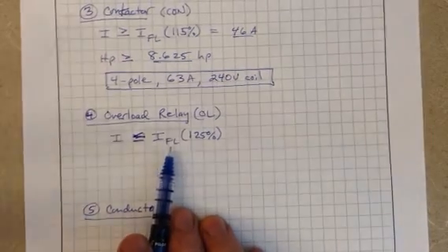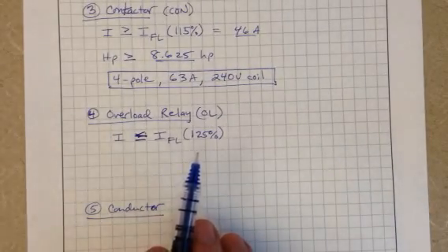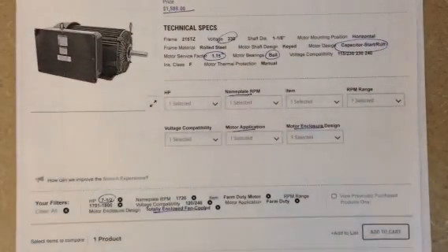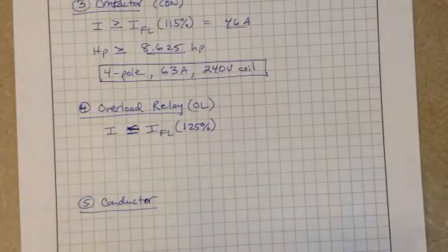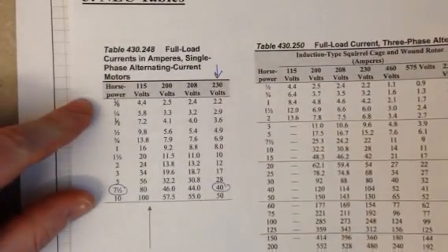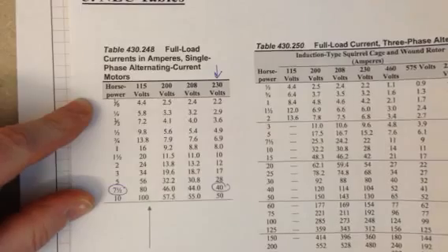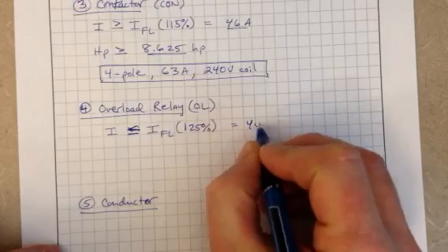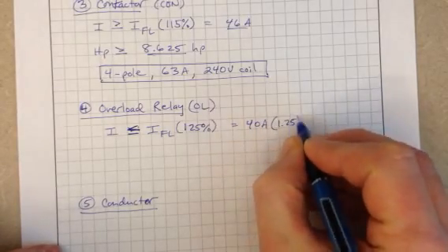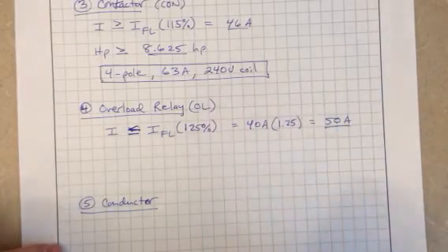I don't have a nameplate current rating in the document online that we show here. It doesn't show us the nameplate current rating. So in that scenario, I don't know what the full load current rating of the nameplate of the motor is. I'm going to estimate, I'm going to use the full load current from my NEC table. Okay, when in doubt, 40 amps. I'm going to base it off the 40 amps. So my 40 amps times 1.25, I have a 50 amp I need to consider.